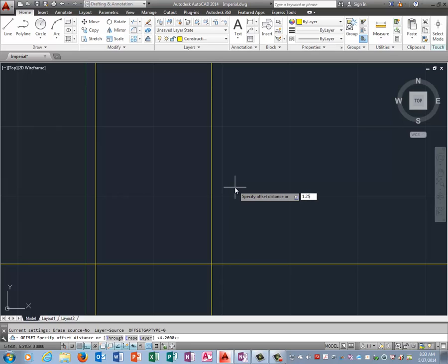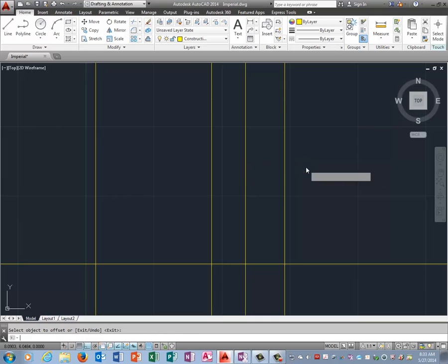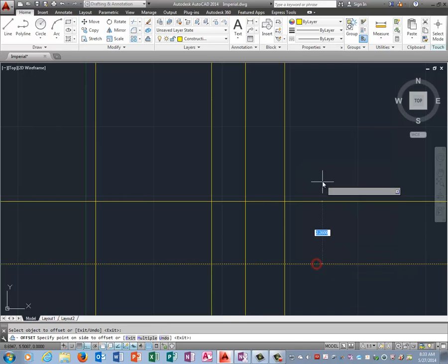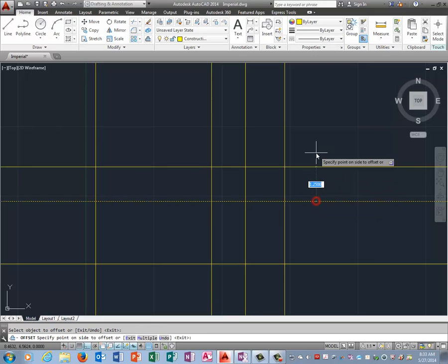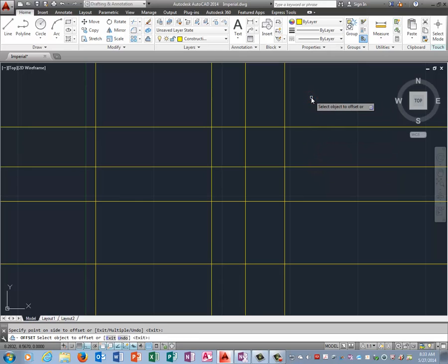Distance between 1.25. Width of the side view 1.44. Height of the front view is 2.26. And distance between 1.25. Width of the top view is always the same as the width of the side view, which is 1.44. I have two perfect squares here, so I know I did that right.